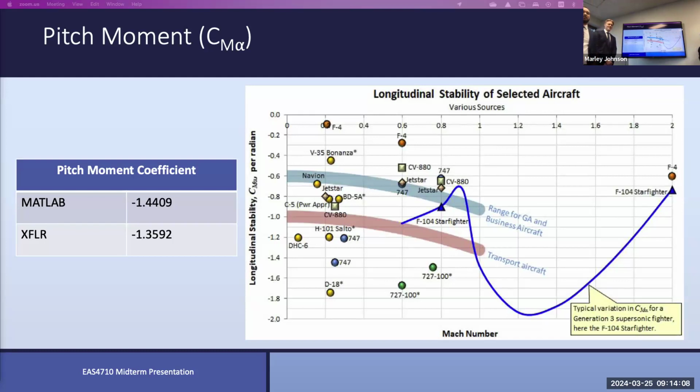When people do a FEM, I ask, how do you know that the FEM is not garbage? So what you've done is use MATLAB to do hand calcs. Exactly, that's what I want to hear. Tell me we validated the XFLR results with hand calcs using equations from the standard textbook from Lewis, Anderson, whoever else.